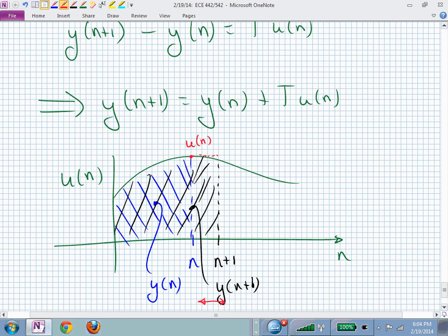And this difference equation came from this process of going from the analog pure integrator into a zero-order hold equivalent system representation of an integrator in a discrete time system, and then pulling that into the time domain.